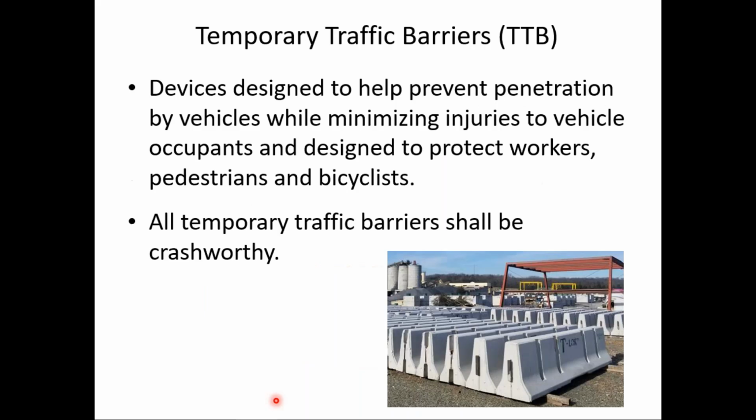If you need that positive protection or shielding obstacles, this is what you need to use, the temporary traffic barriers. These have been tested and proven to be crash worthy and designed to be crash worthy. So I wanted to point out and distinguish that the pedestrian channelizers are not the same thing as temporary traffic barriers. And I think I have a few examples here to illustrate how each would be used.